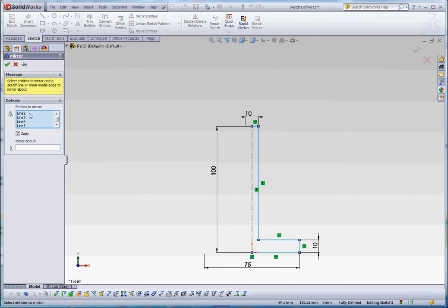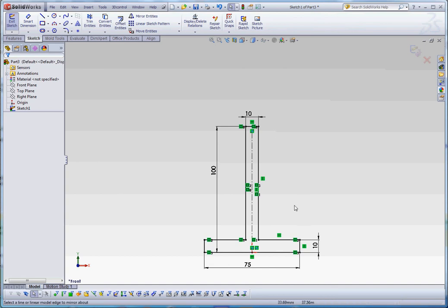And it filled in all those lines up here for us in this blue box. Remember, the blue box over here in our properties palette is waiting for some sort of input. And we can get that input simply by clicking on the objects in our modeling area. We're going to mirror it about this line. Pre-selection, it turns orange. Fully selected, it turns blue. Preview is yellow. And green check mark. Now we have our profile.